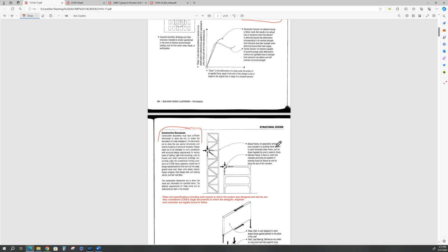All right. Braced frame. A braced frame is a vertical truss, including a building frame system to resist the horizontal shear forces such as those imparted by wind or seismic. That's a braced frame. It's like a vertical truss. We talked about trusses in CNBT 1311. The World Trade Center was a bundled tube with cross braces in it, and it became a giant, tall moment frame, a bundled tube concept.